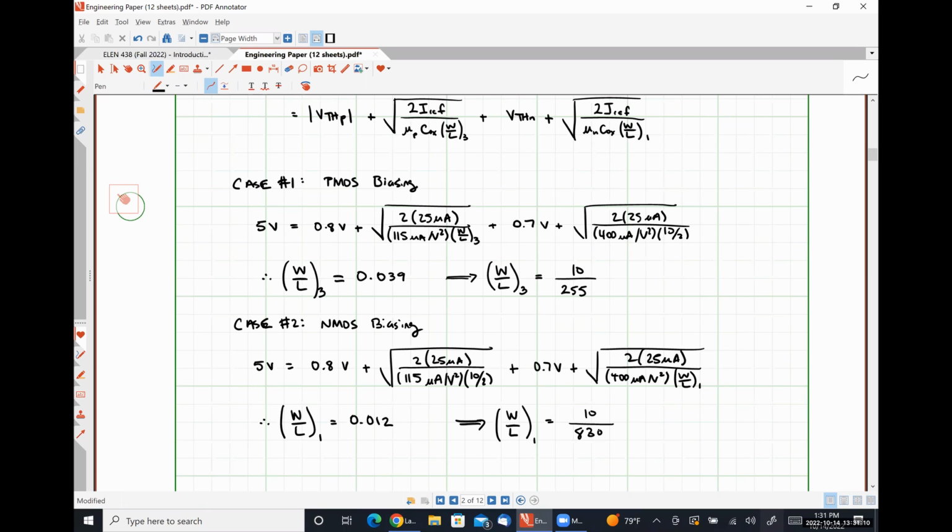The textbook has a mathematical derivation of this. Effectively, what it boils down to is you get on the order of 10 microamps of change in reference current for about every 1 volt in power supply variation. So if you're trying to establish a 25 microamp current and your power supply fluctuates by as much as half a volt, you're getting plus or minus 5 microamps of current added on to your reference, which is a large percentage. Yes, exactly right. It is still quite significant, okay?